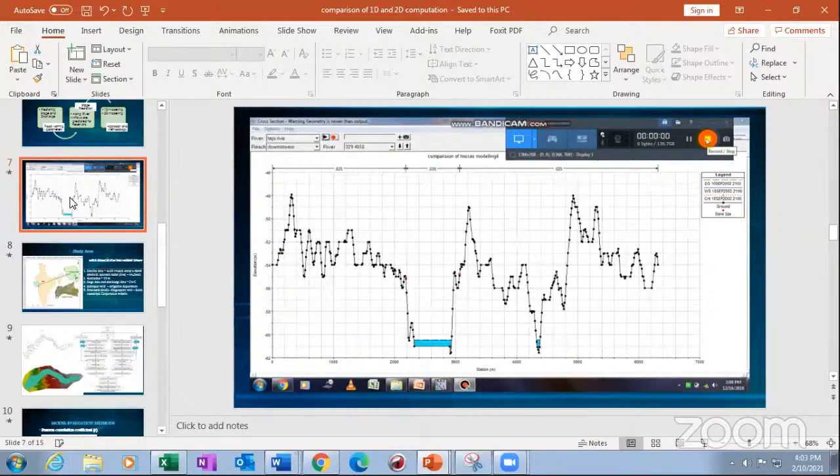But it cannot show you how much area is going to inundate unless you consider that area itself as a cross section. Okay, so that's one thing. Second thing, HEC-RAS 2D comes with so many advantages. You can even understand the flood inundation area. You can see how much depth is going to come with a certain amount of water released from the upstream. But what is the problem with HEC-RAS 1D and 2D?